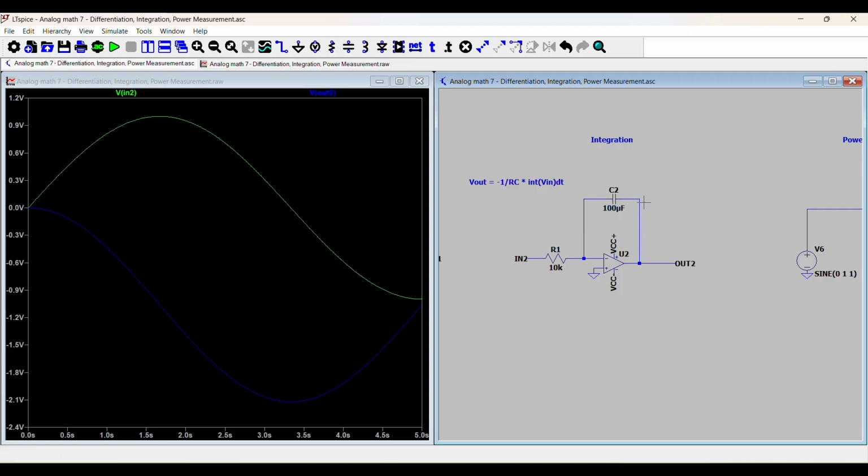And then the op-amp is pulling this output, increasing or decreasing it, to make sure that the capacitor, when it differentiates this output, creates this same current. The capacitor is pulling and pushing voltage over here, and it can only swing to the supply rails. So if the inputs are too big, it'll clip at one of the supplies.